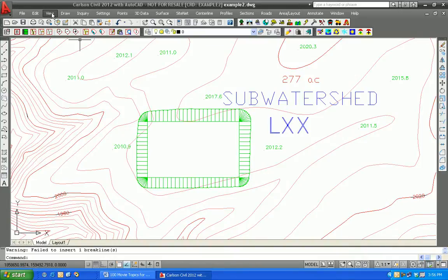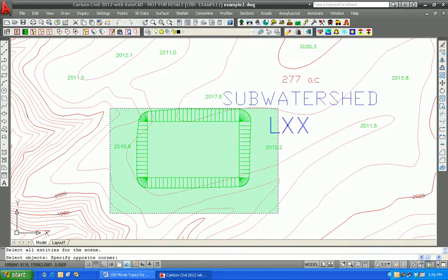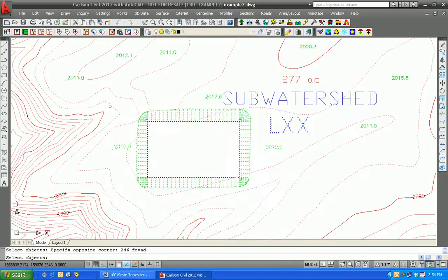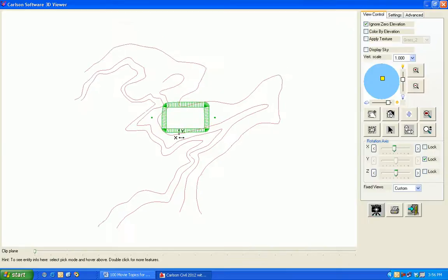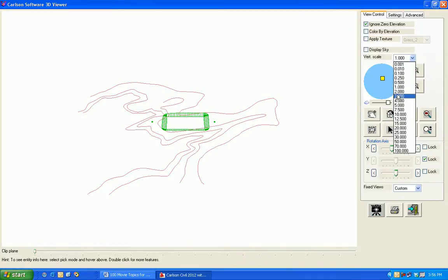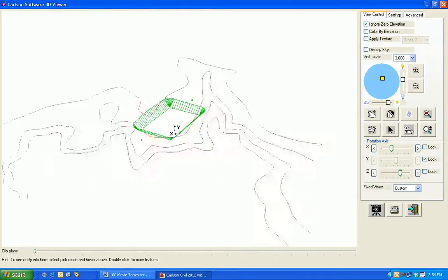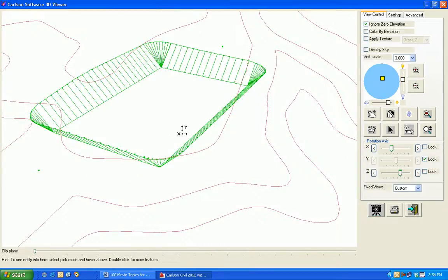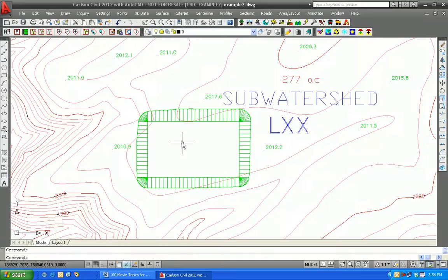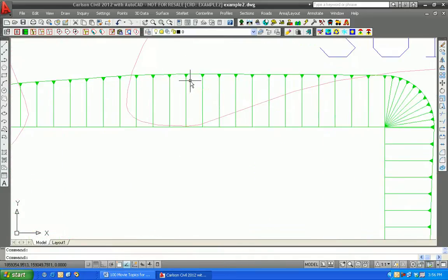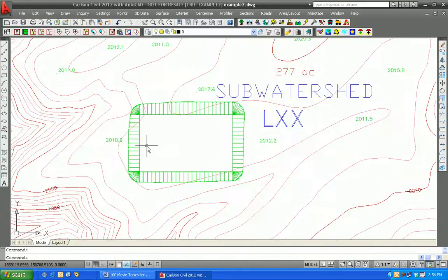And you can see if we go to the 3D viewer window, I'll carefully crossing select the elements that we have, especially if we exaggerate it, a nice deep pit drawn here with 3:1 slopes all the way around. And in plan view, you'll notice we have these slope direction arrows indicating the downward nature of the slope into the pit.